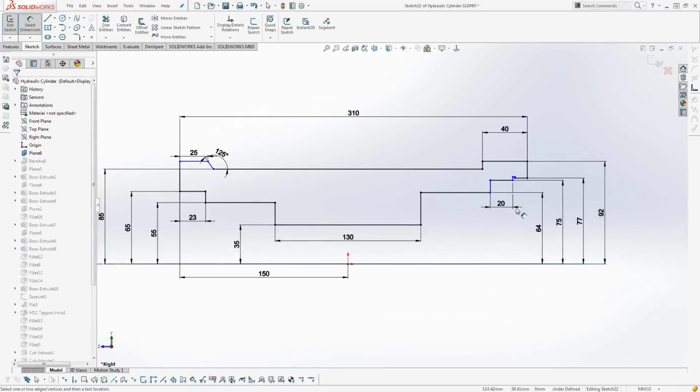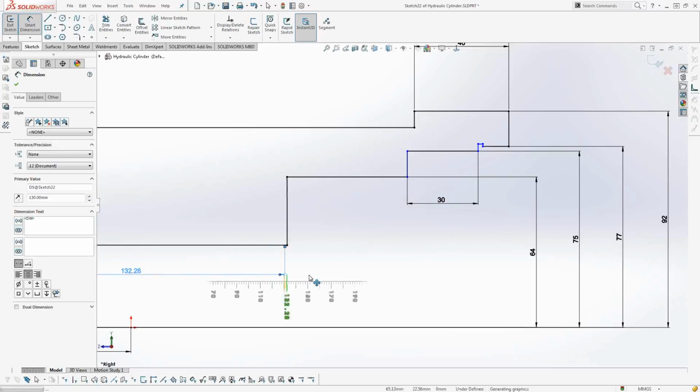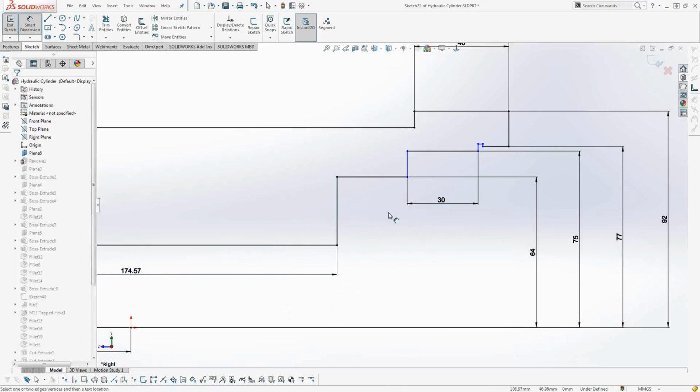Similarly, if you guys remember Instant 3D in SolidWorks, well, they've also included something called Instant 2D. The way Instant 2D works is that you can select an existing dimension, and you can even use these little blue pinballs here to drag the dimension along a scale to dynamically change the shape of your sketches. It's a really convenient and easy way of modifying your sketch entities.